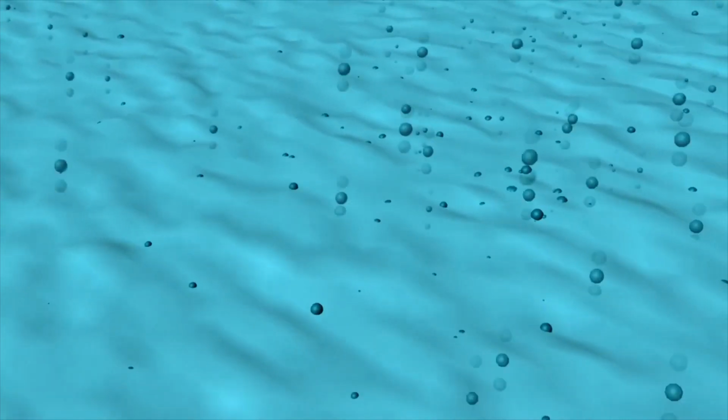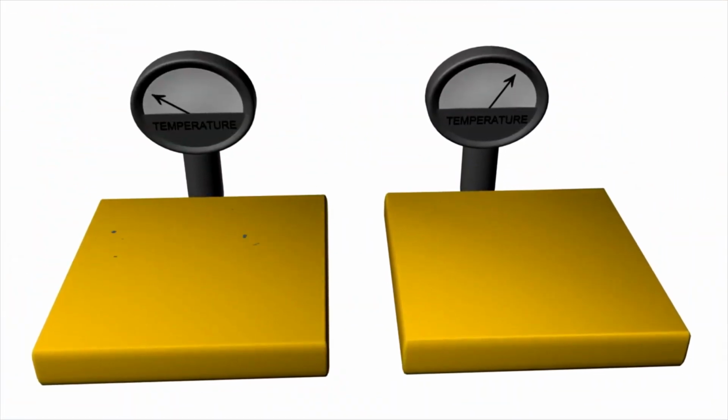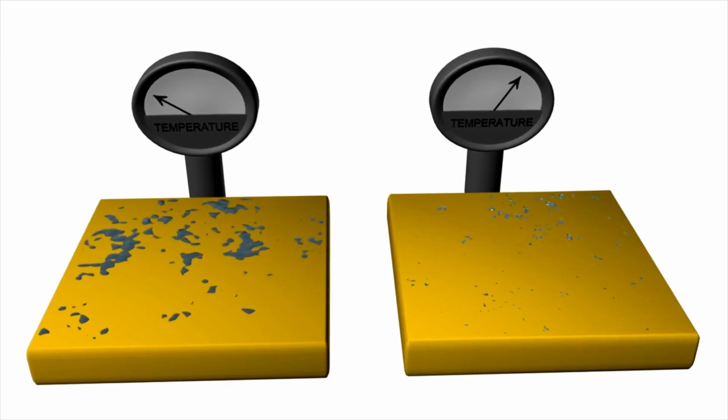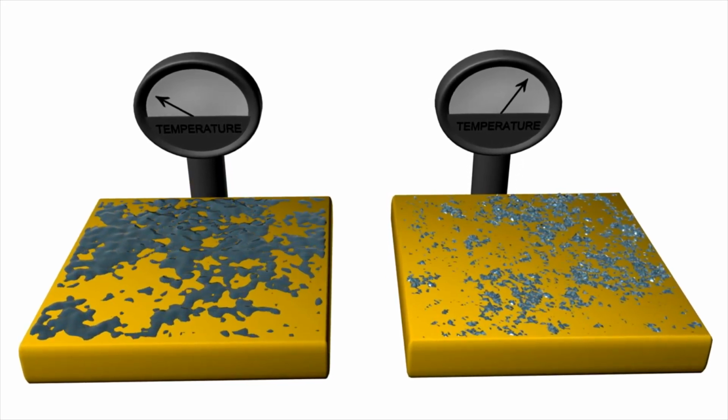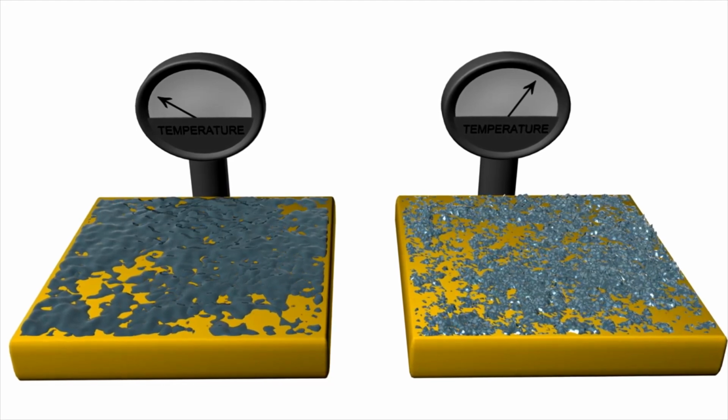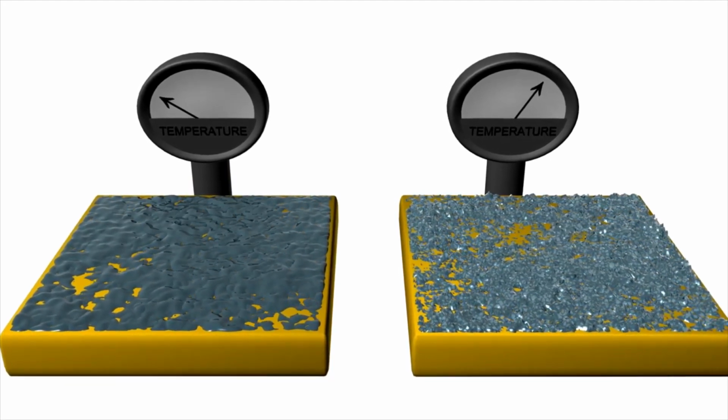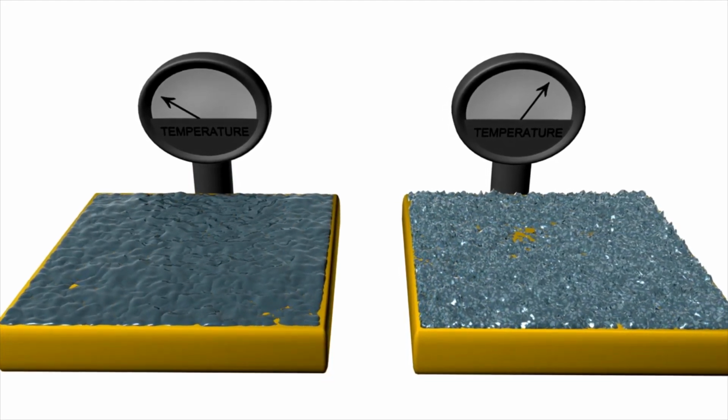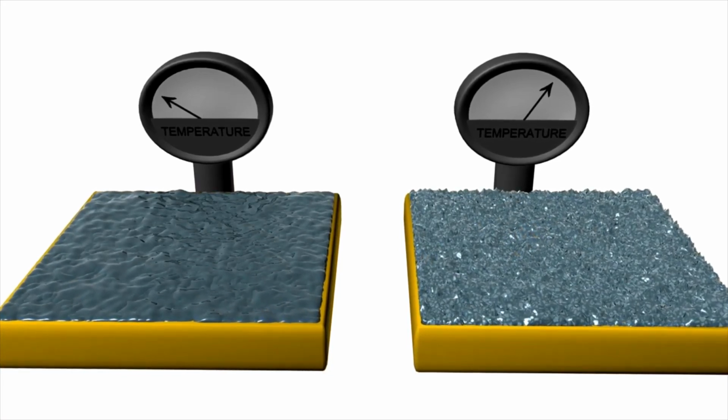However, when the gas pressure is too high, then the energy of the atoms arriving on the growth substrate is not high enough to allow the formation of an ordered crystal structure. The resulting film may be with low density and amorphous, which in some cases may be the actual goal. Anyhow, the crystallinity of the grown films also depends strongly on the temperature of the substrate. Films deposited at higher temperatures are normally crystalline, while films made at lower temperatures are rather amorphous.